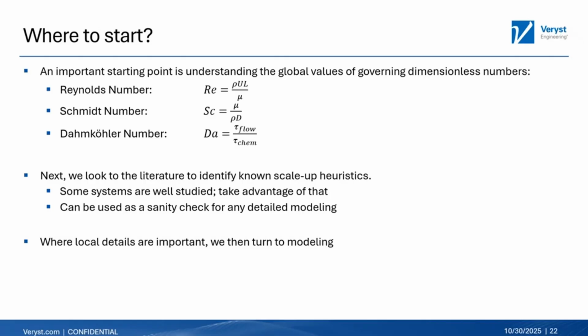Many systems that are commonly encountered in industry are well studied, think the mixing tank or static mixers, and we can take advantage of that. At the very least, as a sanity check before we go into any more detailed modeling, we can understand what we expect in terms of conversion rates, heat release, et cetera. And then when we have done all that and we seek to further understand local details, then we turn to modeling.